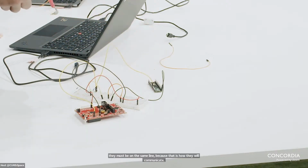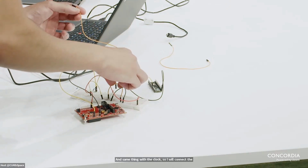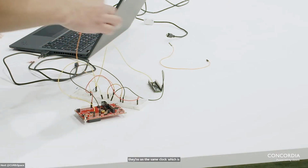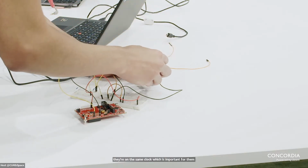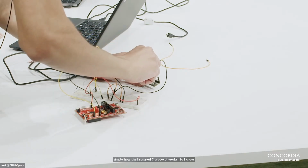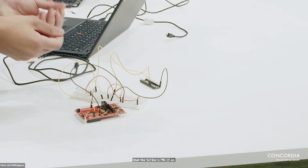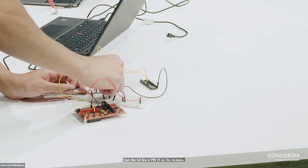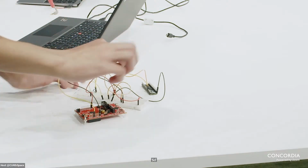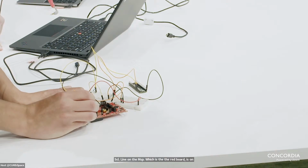And same thing with the clock. So I will connect the clock line to both boards, and that will make sure that they're on the same clock, which is important for them to be synchronized with their messages. And that's simply how the I2C protocol works. So I know that the SCL line is pin 19 on the Arduino, and the SCL line on the MSP, which is the red board, is on pin 1.7. 1.7. And there you go.